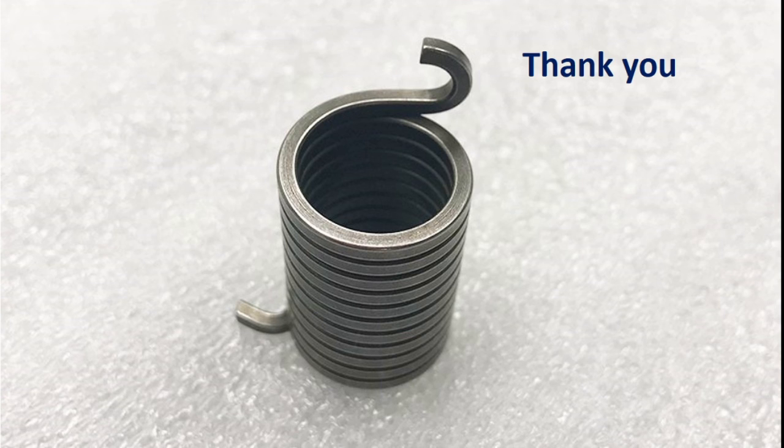Also, if you want to make a rectangular spring by utilizing rollers, the rectangular shape is converted into a trapezoidal shape. With the trapezoidal shape we can't get the higher resilience, so we can retain the higher resilience of rectangular springs with the aid of the lathe process.